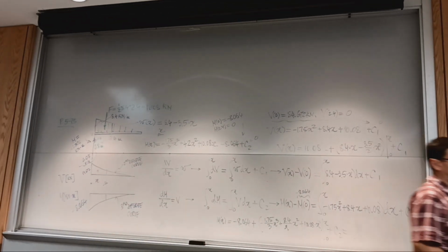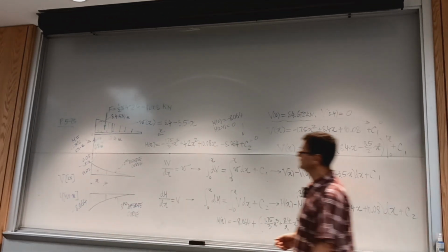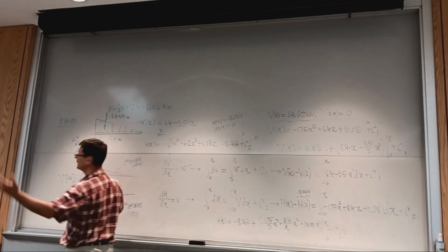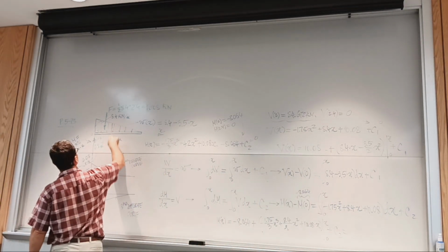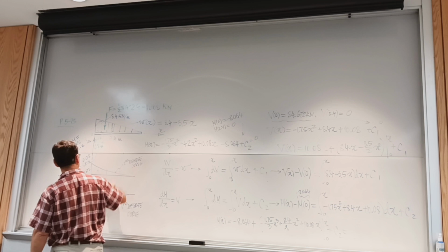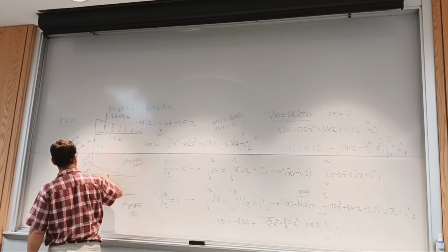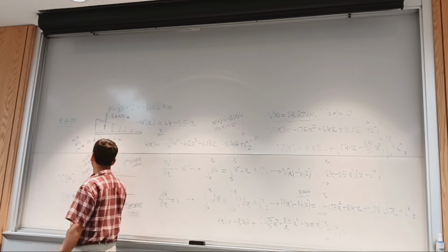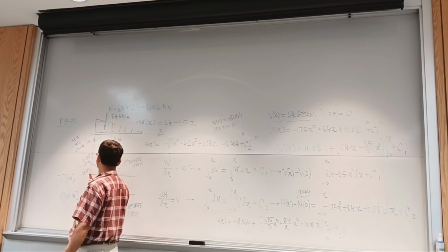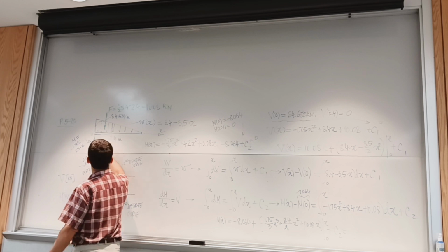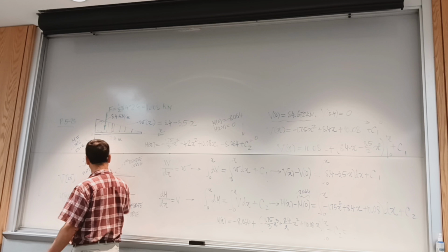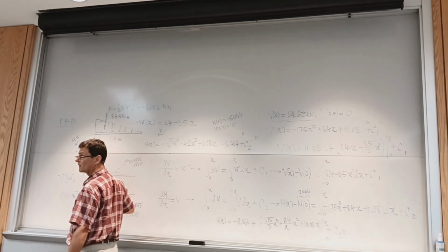And otherwise, if somebody wants, like in the middle of the beam, 1.2, how big is the moment? Okay, so how do you get that? Well, you'd have to at least integrate from 0 to 1.2 to get this area to find this moment.